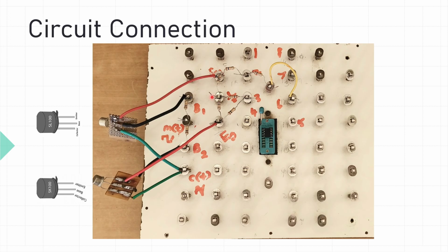In order to avoid multiple single strand wires, I directly connect 10K to pin number 2 of the op amp, and between pin number 2 and 6 I have connected one 10K here.